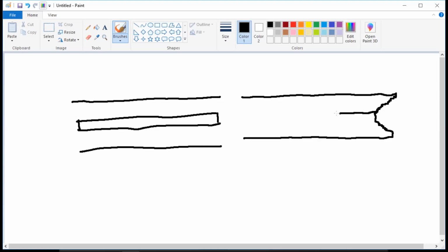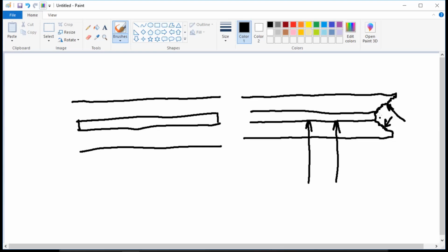And the center conductor is here. But it burns so cleanly that I still have insulation here and here outside the cable. So when I introduce a DC high pot adapter or DC voltage on this inner core, it doesn't have enough voltage to get over here to ground because of this insulation still in it. That's an open. Make sense? The conductor's burnt completely in two.